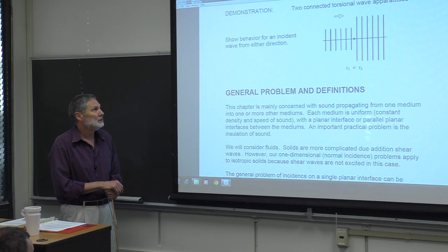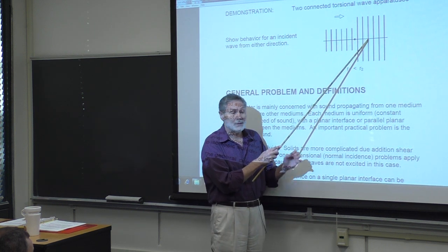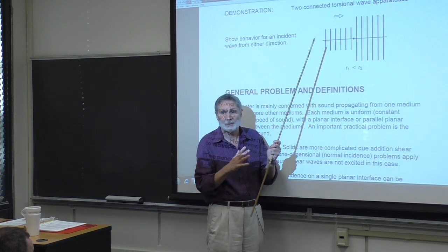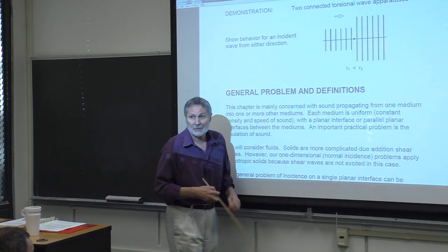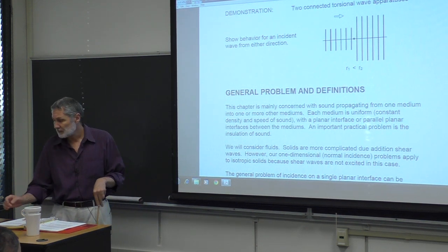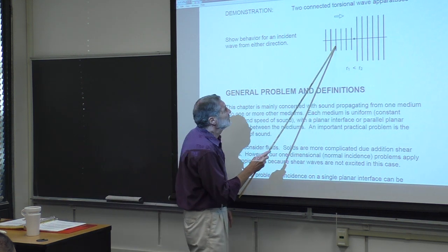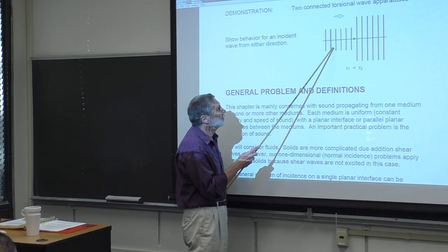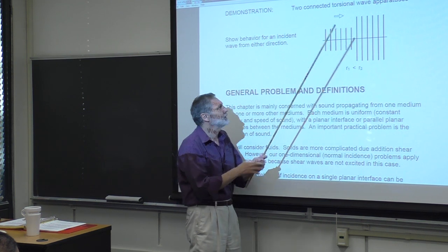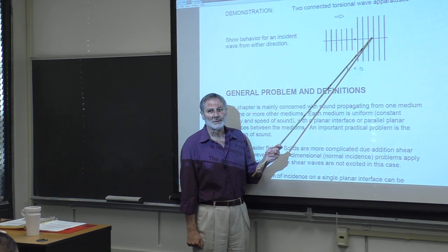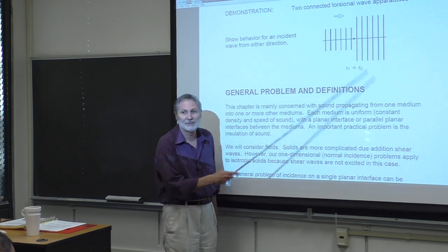So, greater stiffness on the left. You could use a rod of a bigger diameter. You can solve for that specific value, and in that case, you should get no reflections. And it doesn't matter, of course, which way you're going. An alternative is to, wait a minute. What did we say here? We've got greater inertia here. Yeah, we want the diameter to be less here. We want it to be less stiff, okay?